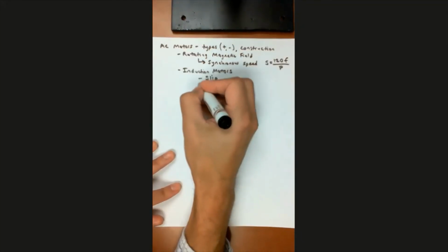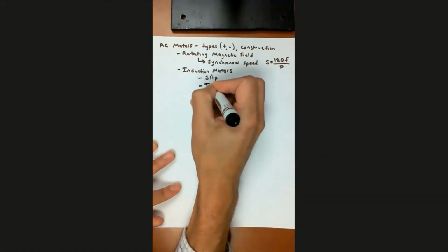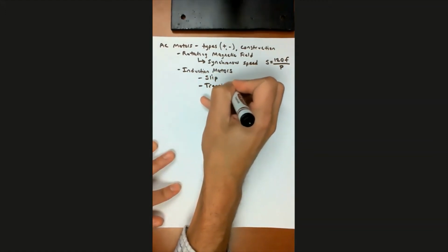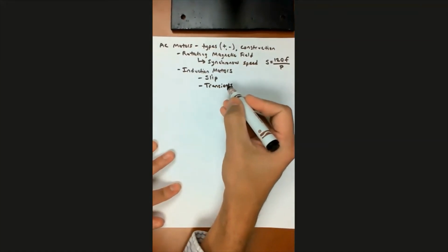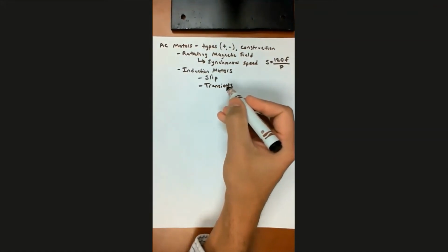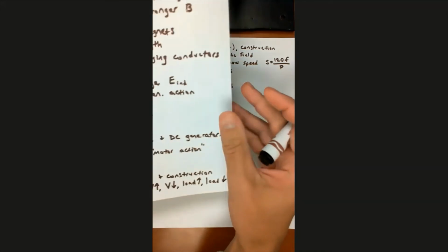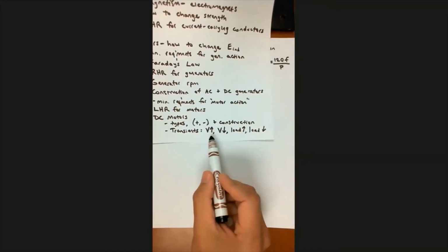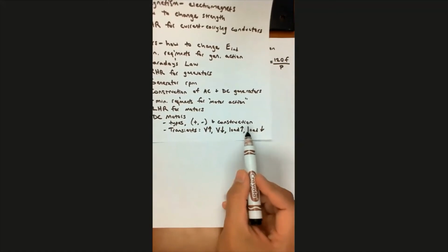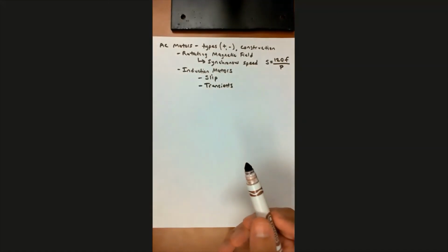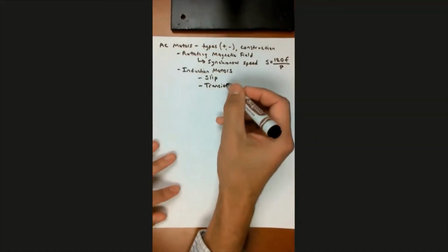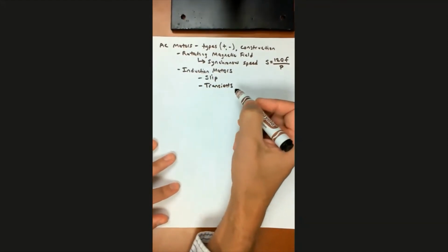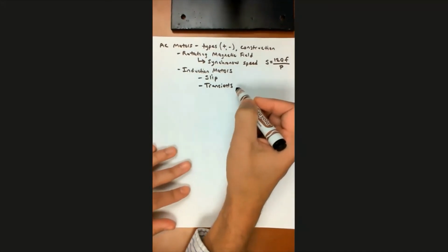We talked about transients for induction motors only. Transients, kind of like transients for the DC motor. For the DC motor, the different transients were the voltage increases, the voltage decreases, and these are the applied voltages, or the load increases or the load decreases. The way we control the speed of an AC induction motor is not by the voltage, not primarily at least.